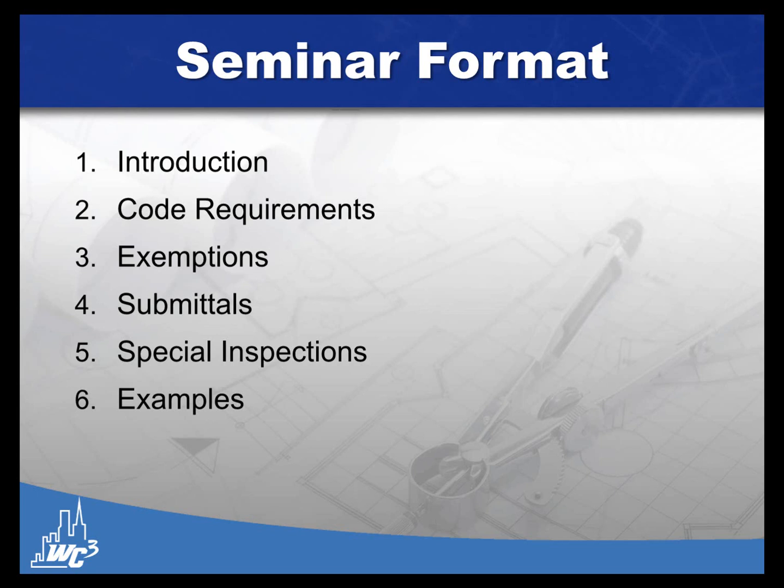We're going to cover exemptions. We'll go over what are the minimum submittals that you should be providing to the enforcement agency, to the jurisdiction. We'll talk about when special inspections are going to be required on this seismic restraint. And then we'll go over a couple of examples, and we'll discuss where you can find more examples and figure out how to do designs for different elements if you're responsible for putting those together.